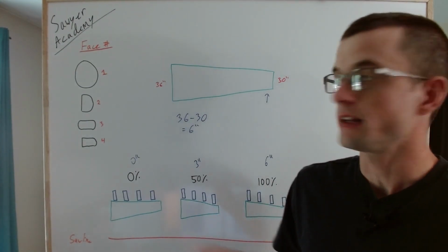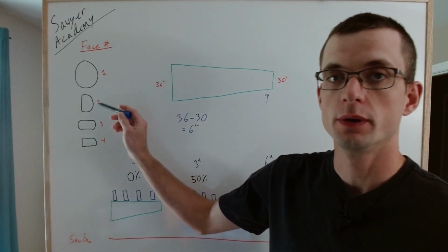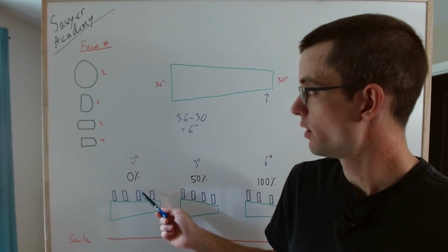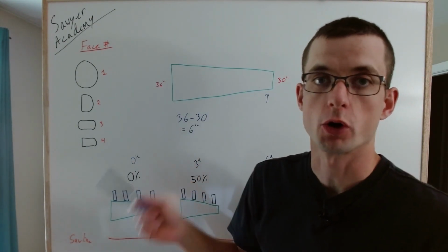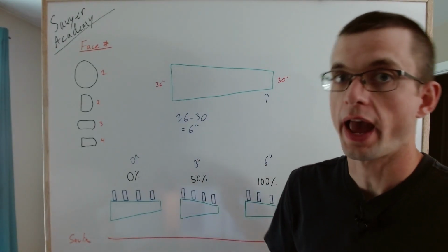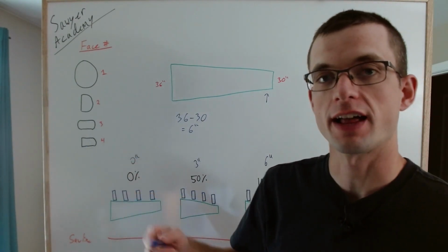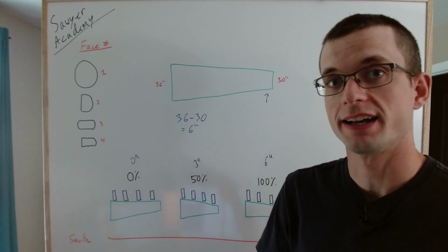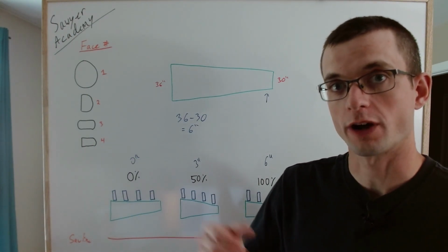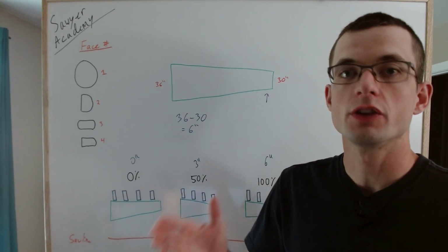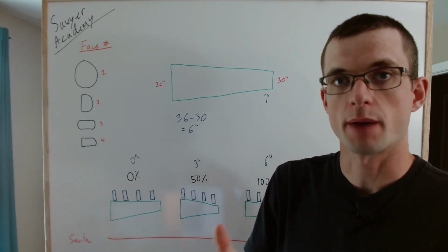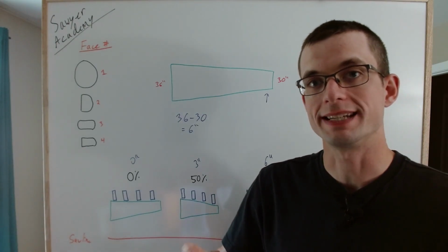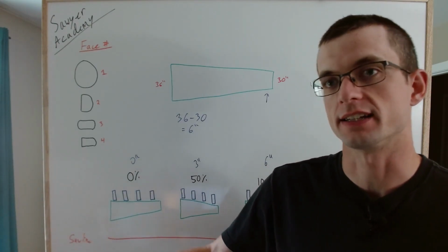Once face 1 is cut and you're on to face 2, now you have a flat side that's either referencing your bunks or the bed of your portable sawmill. So on face 2 and face 4, when we're referencing that flat side, we do not want to put a taper on. If you were to apply a taper to face 2 or face 4, referencing a flat side, your entire cant would come out tapered. As well, every board out of that cant would also be tapered on the width for the entire length.